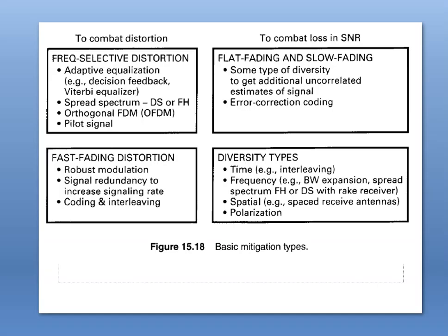Basically in electromagnetic communication, we are supposed to use three types of polarization. One is linear, second one is circular, third one is elliptical. Linear again consists of two methods. One is the vertical polarization, second one is the horizontal polarization. And if the magnitudes of the electric field and magnetic field intensity are the same with respect to the x and y axis, it comes under circular polarization.